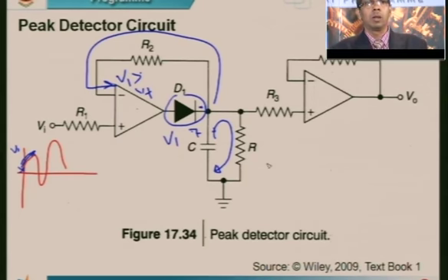The design goal in finding the value of this resistance is how quickly you want the second peak to come at the input. So it should not discharge till that time. It should only discharge when the input peak also falls. If I have a very high time constant in the discharging, the voltage here remains constant till the next peak comes, or it discharges very slowly. The moment the next input peak comes up, if it is larger, the diode again becomes forward biased because the voltage at this pin is now larger. The diode is forward biased, it again starts to charge and then it can catch the new peak here. This way, while the capacitor is charging, it can go on catching the peak and stay at that peak.